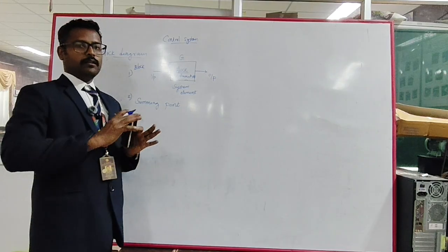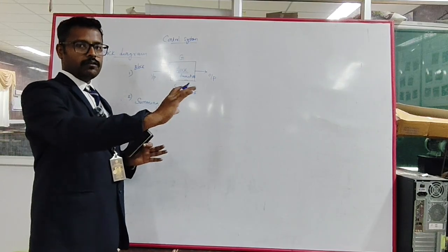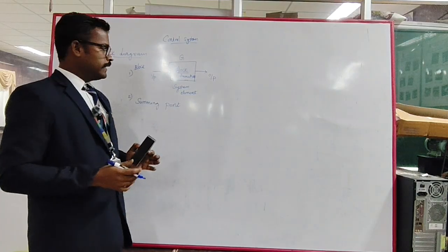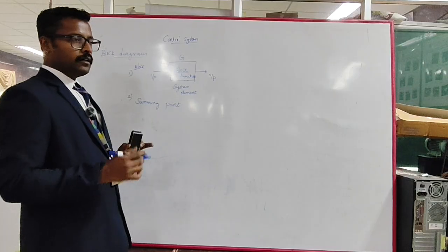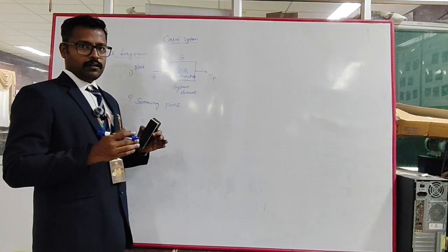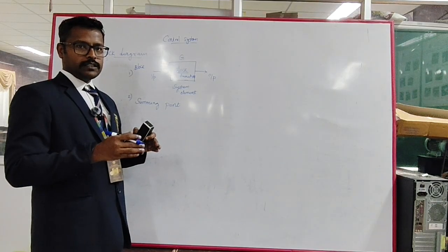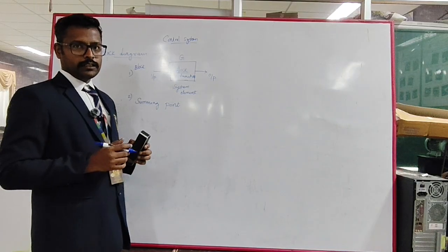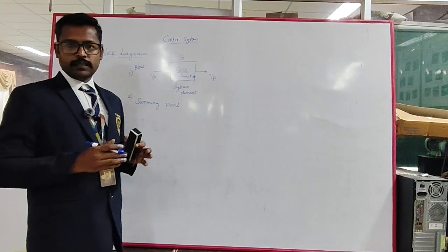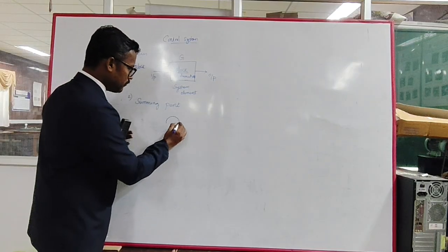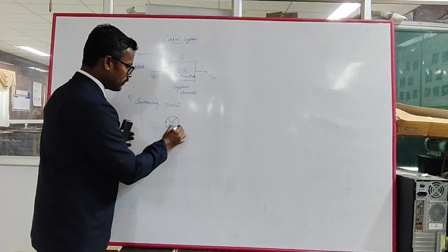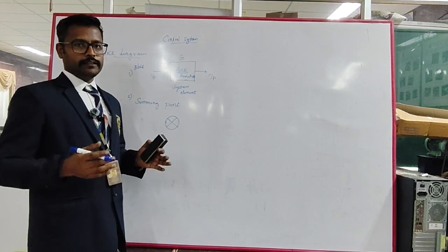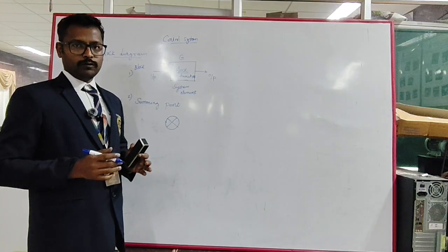We know that in a control system it may be feed forward or feedback, or feedback plus feed forward. At the summing point, if more than one signal is coming into the system, we sum those signals. It is represented by a circle with a cross. The summing point can sum n number of signals into one output.